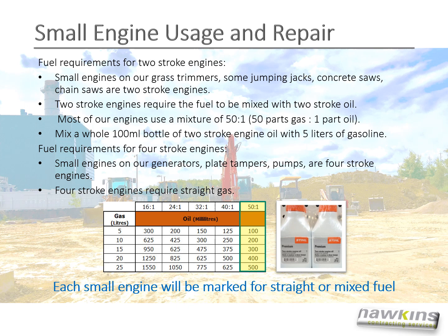gasoline. Four-stroke engines. Some engines on our generators, plate tampers, and pumps are 4-stroke engines. 4-stroke engines require straight gas. Each small engine will be marked for straight or mixed fuel.